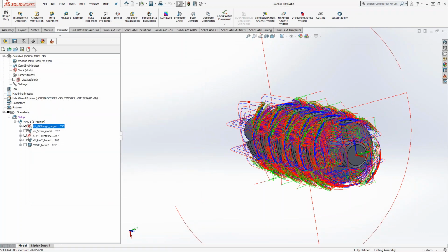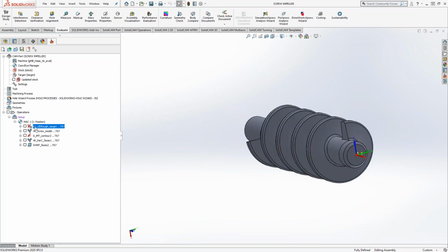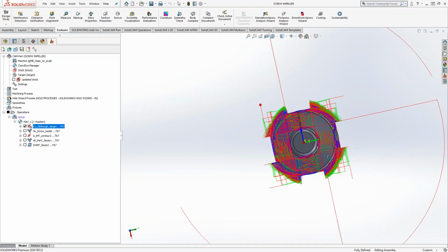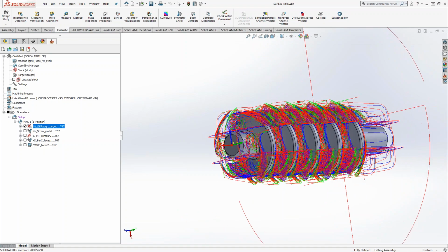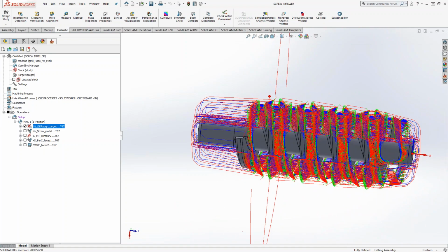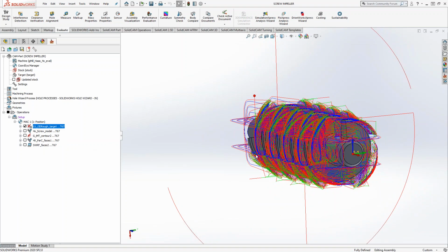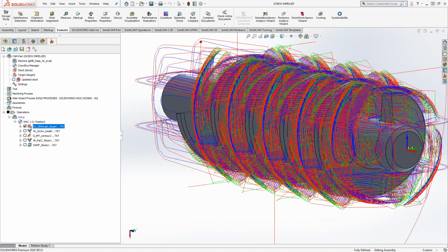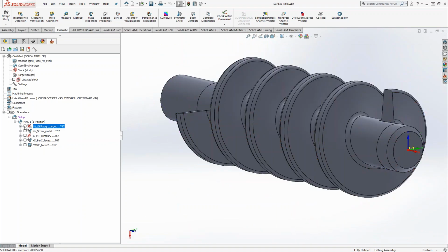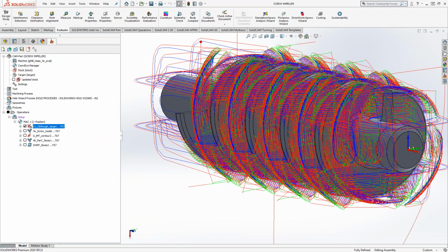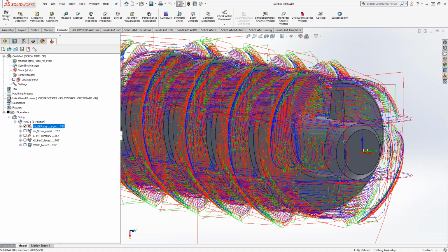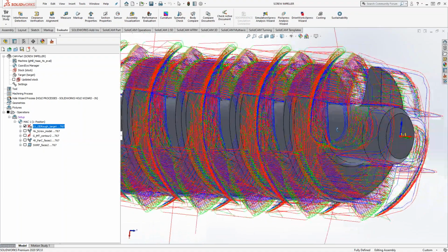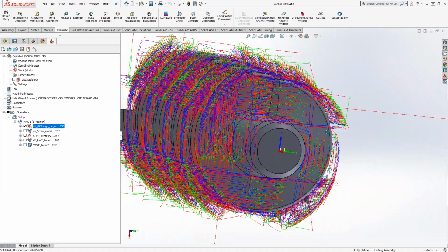Yeah, and like I said, to Brad's point yesterday when he was asking about this, this is one of my favorite features about 3D iMachining, because I can just kick it over at 0, 90, 180, and 270 and get all the material pretty much eliminated out of there without having to do much thinking or much work. Now, coming to the finishing side of things, then you can really fine tune your finishing in there.